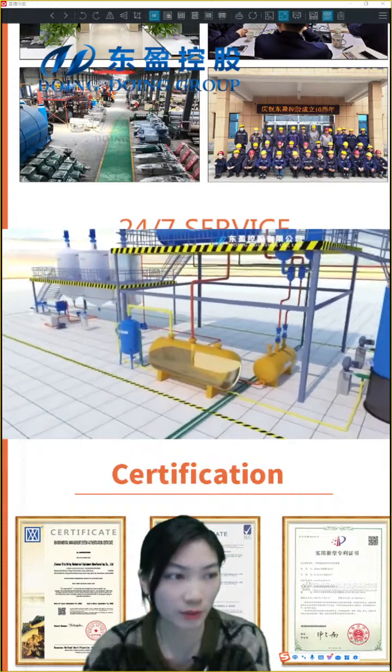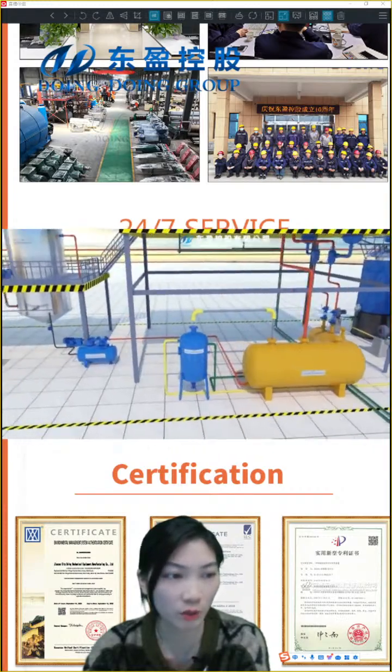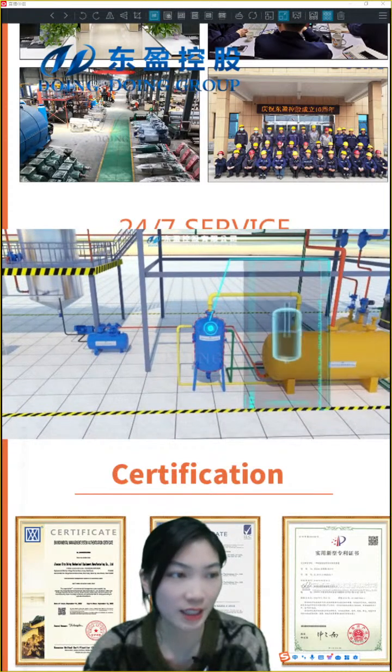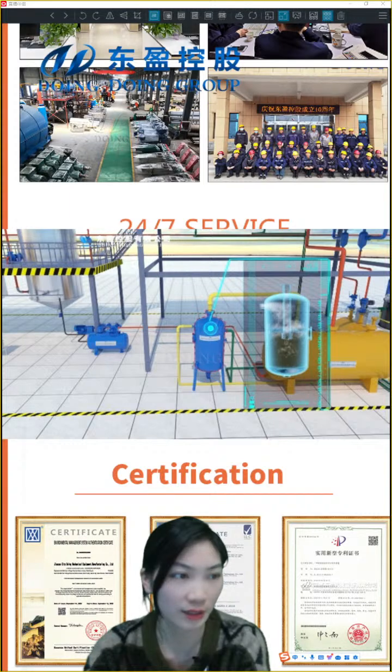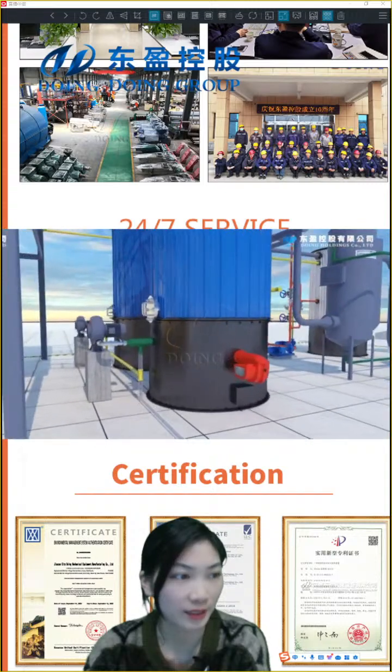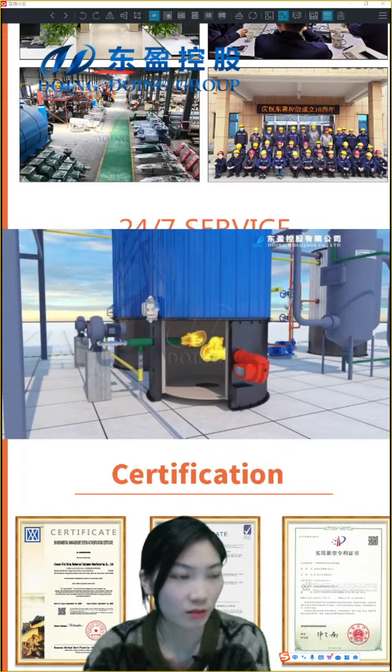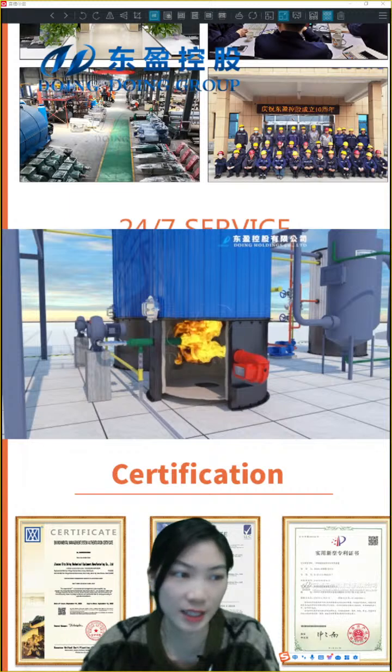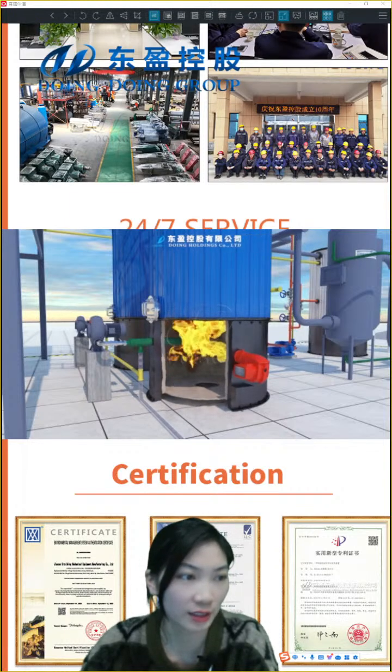Outside the tubes is water. The water is recycled water. And this is a water seal. This water seal will avoid the syngas flowing back. It also cleans the syngas. The syngas can be recycled as heating fuel, used in our reactor heating.